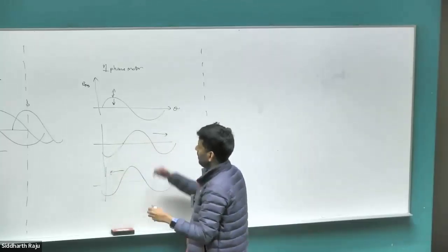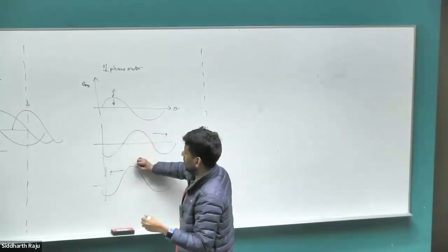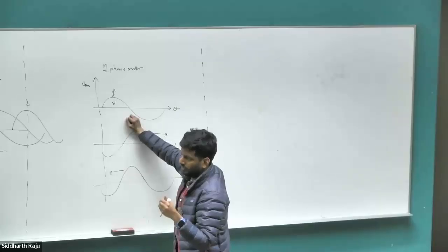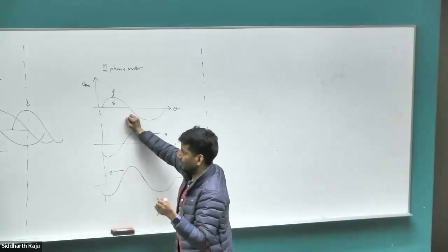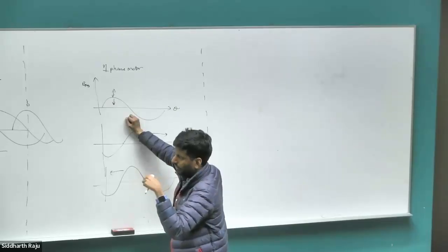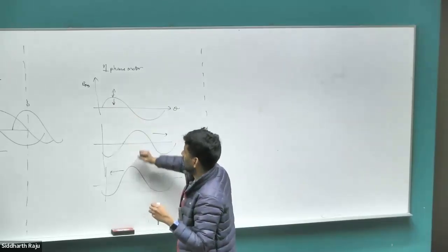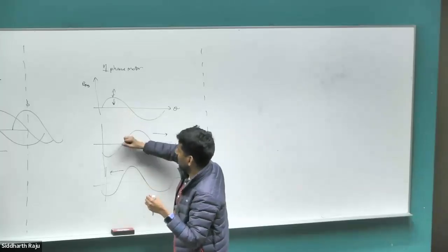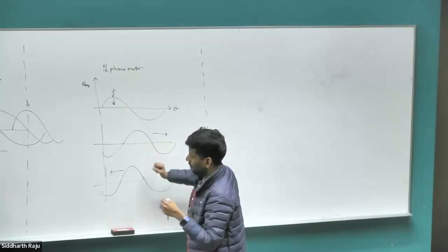So we could mathematically decompose a single wave into two components. We did parallels with what we do when we do our experiment for estimating the speed of sound, where we have a standing wave. We have a forward traveling sound wave interacting with a reflected reverse traveling sound wave to create standing waves. Here we do the opposite. We do have a standing wave and we decompose it mathematically into one forward traveling wave and one reverse traveling wave.